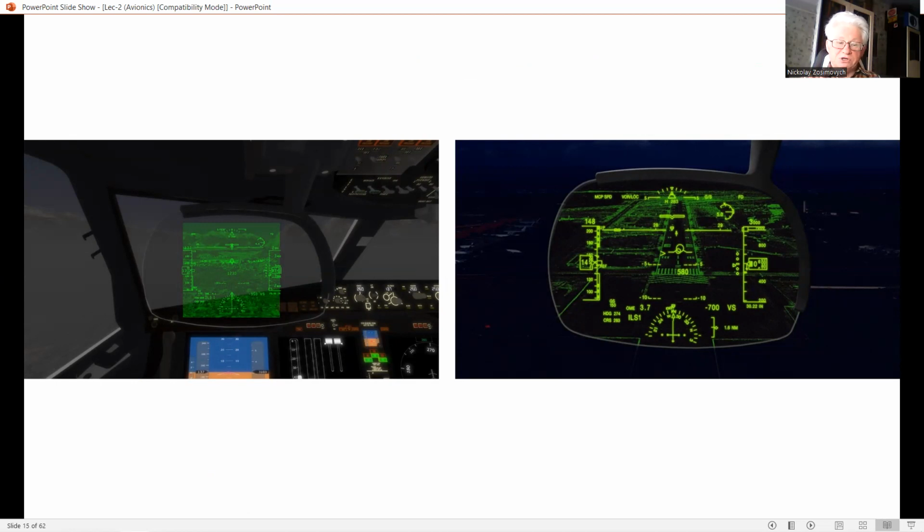A large horizontal field of view is particularly important to enable the pilot to look into a turn when the HUD forms part of a night vision system, and the only visibility the pilot has of the outside world is the FLIR image displayed on the HUD.